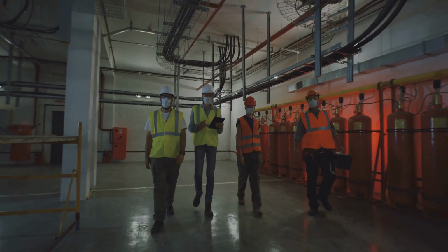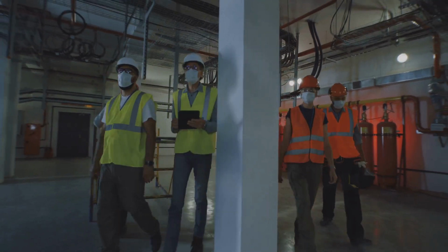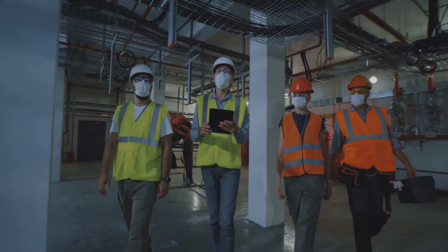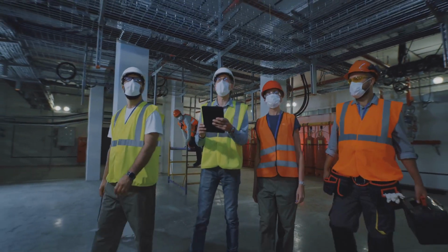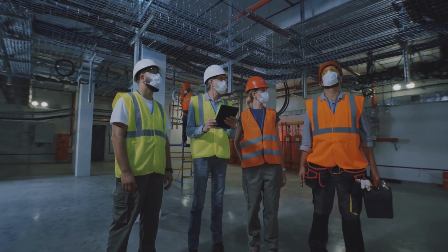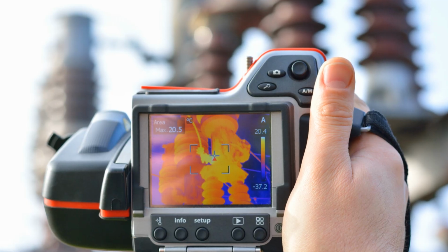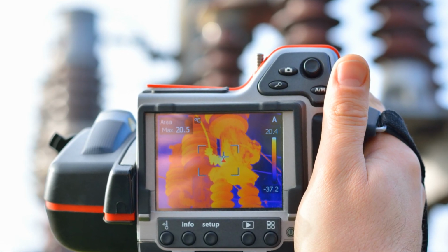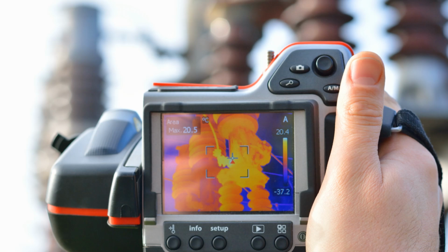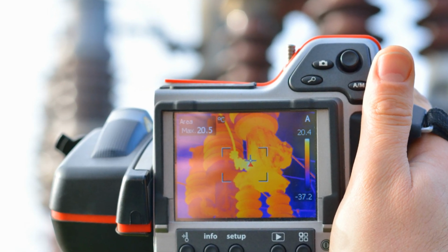Visual inspection remains a fundamental yet often overlooked step in identifying potential failures. While thermal imaging, vibration analysis, and ultrasound testing provide advanced diagnostics, a direct visual assessment can reveal critical issues that technology alone might not detect. Visual inspection reveals loose connections, identifying improperly secured electrical or mechanical components that can lead to overheating, vibration, or failure.